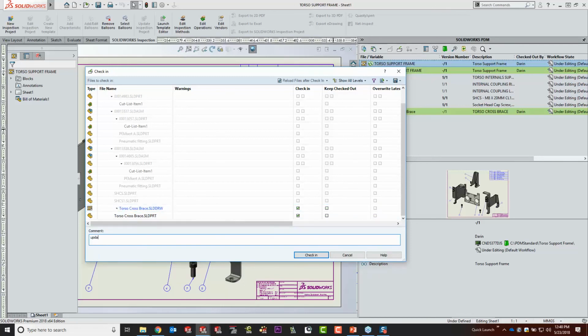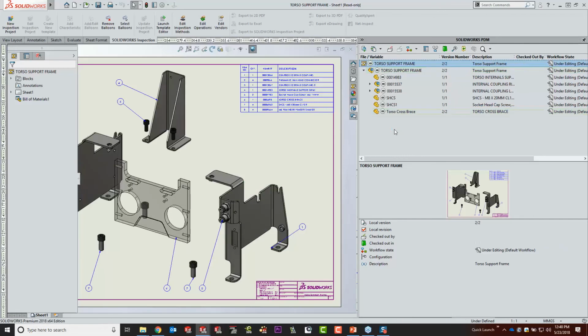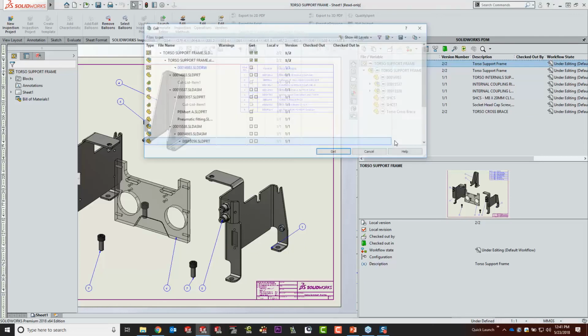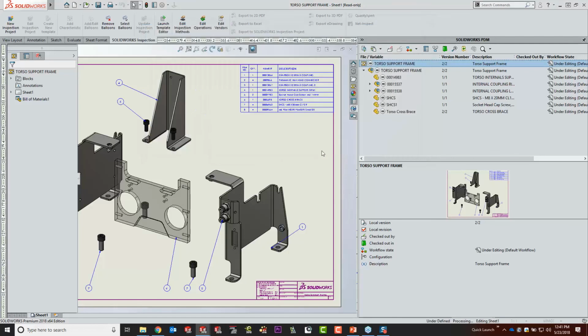All we did here was we updated the holes, and these innocuous little comments become powerful tools. Because now when I go ahead and check the feature history or the revision history of these files, which I'm now looking at the latest and greatest version based on my equal symbol, I can go back in time if my permissions allow, and I can see my comments listed indicating what version is what. Here in SolidWorks, I can actually go back to the previous version at any time I want to, and it'll backdate me to the original one of 2.